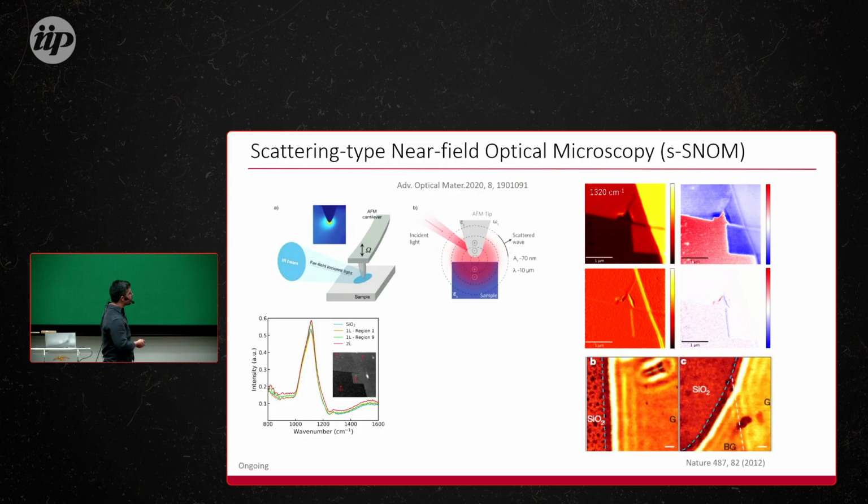Something that has been reported is that this is graphene, where you have a gate. So it's a pristine graphene, and they just make a device and apply a gate. And they were able to observe some very nice features that start to show up here, which are actually plasmons, because we are doping the material because of the voltage that you are applying. So basically what we believe we are observing in our result is that we have some plasmonic effect as well that is naturally appearing in the material because we doped the material with boron.